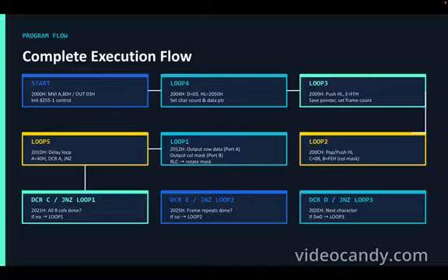Next is loop 3, which rotates through the columns. It activates one column, because that's how the LED matrix works. We can only activate one column at a time, and we loop through all of them, turning on one column at a time at a very fast pace.